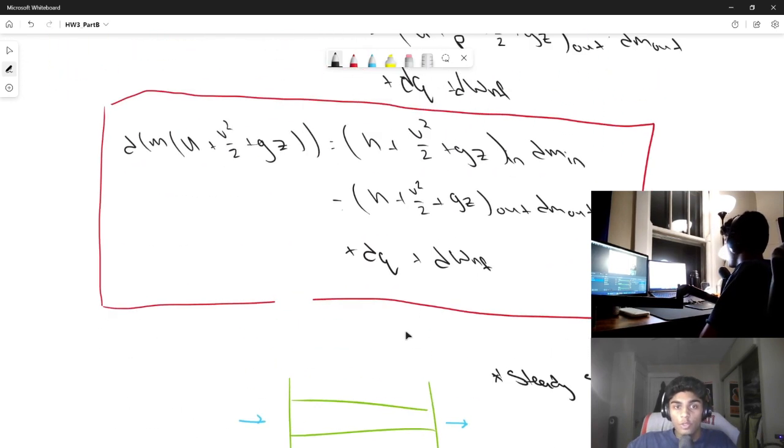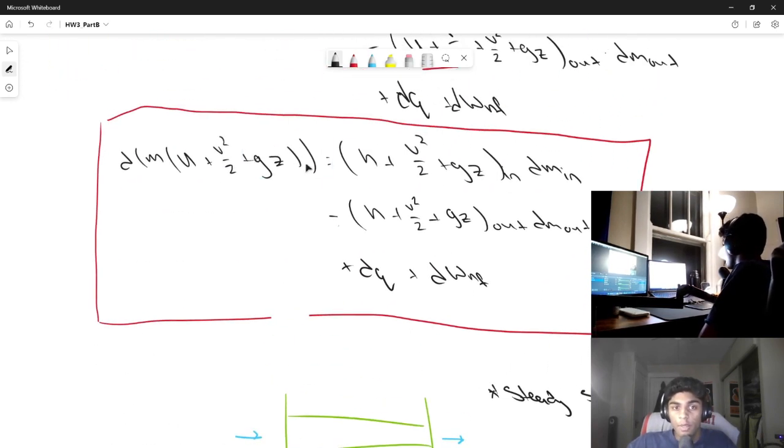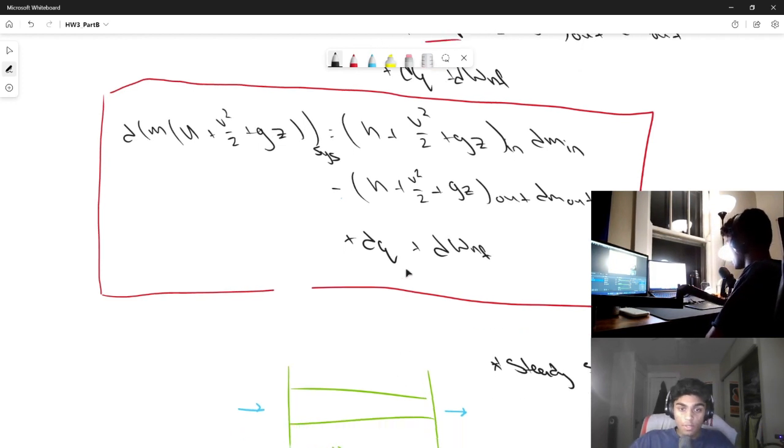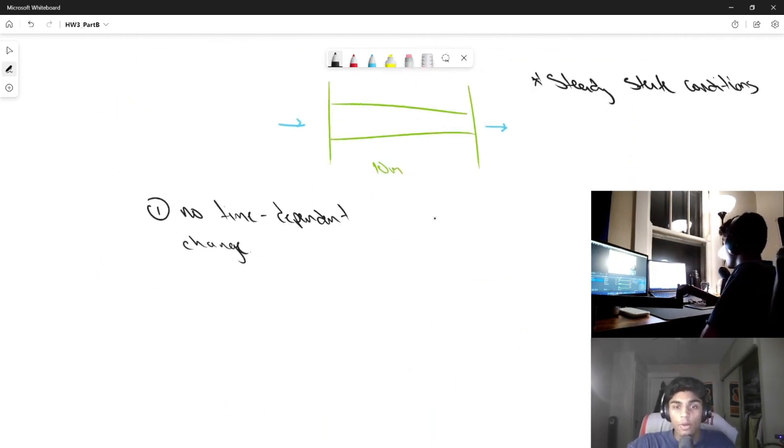So with respect to our energy balance here, this is for our system, and all of this is just going to be zero. There's no change within our system. Everything that goes in goes out, and so there's not going to be an accumulation with respect to time. Conversely, the second thing we want to assume is there is no change in mass.